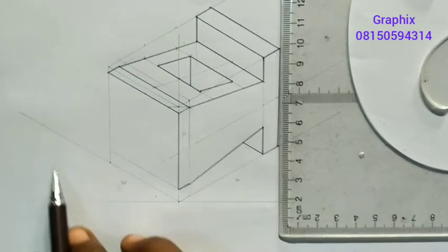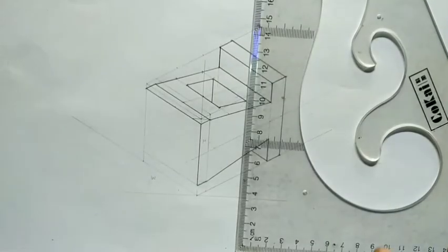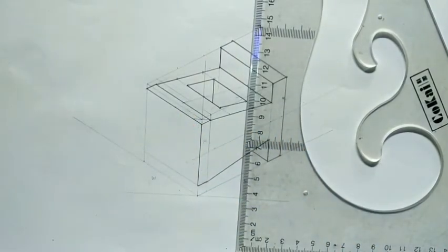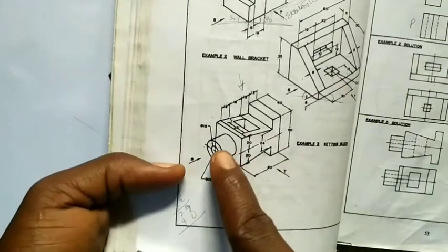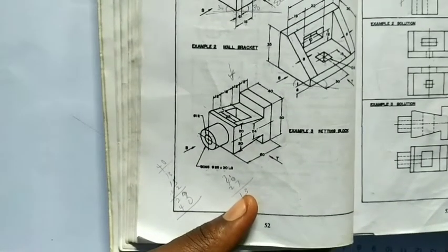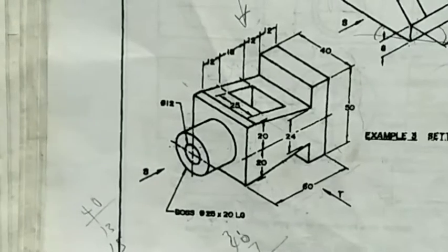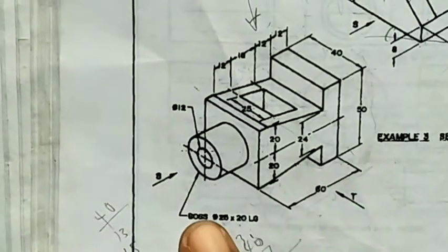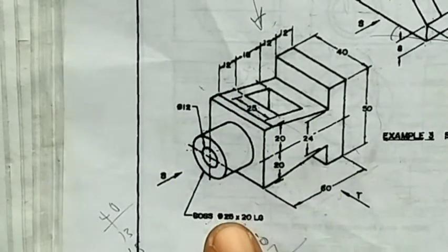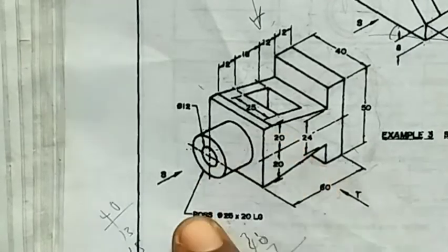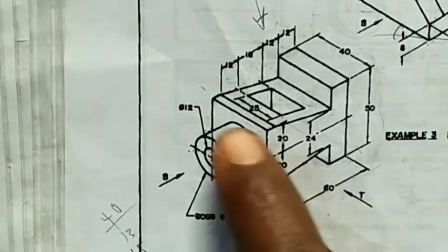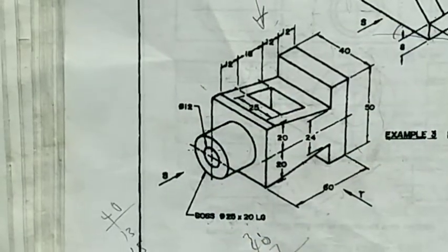So the way I'll draw my circle here is that what you want to do is to draw a circular figure here, right? When I mean a circular figure, I mean this circular figure, like a pipe being protruded. Now if you look closely, you see something here. It's telling me that the boss, the diameter of this circle, is what? 25, and the length at which it is being protruded out is 20. So the length from here to here is 20. The diameter of this circle is what? 25, right? So let's start.